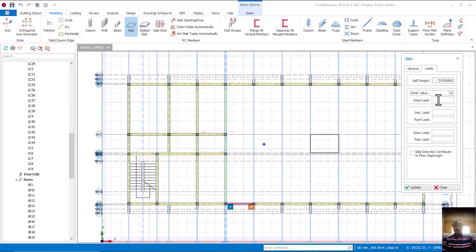My additional dead load, how we get this dead load is that what this place is telling us is what is the additional load, because the self weight of our slab has already been calculated, which is 3.6. In terms of the dead load, this place is talking about additional load apart from the slab itself. After casting the slab, are we together?